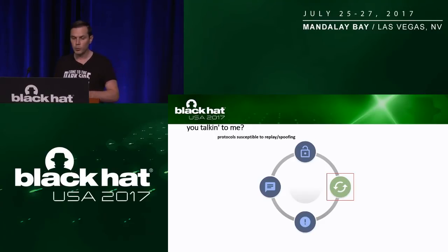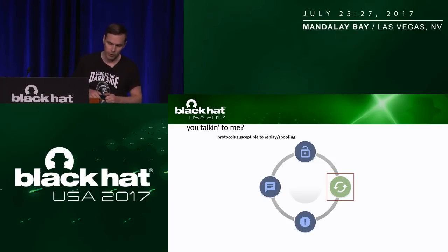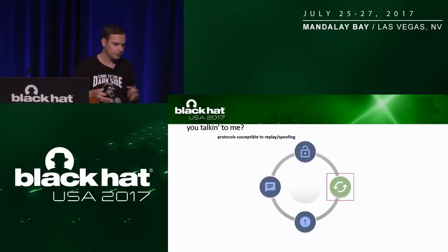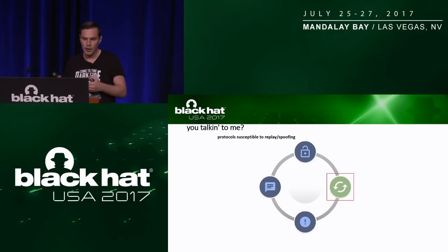The same issue also leads to replay and spoofing topics. The point here is because there are no dedicated security functions, like cryptographically supported security functions, in the actual building automation control protocols, you have the regular replay and spoofing issue in there as well.